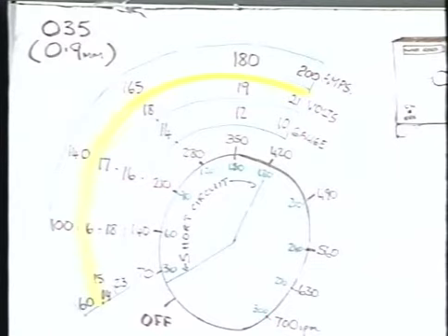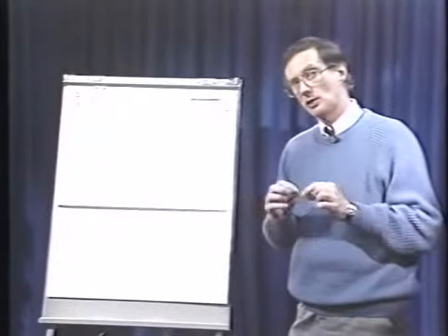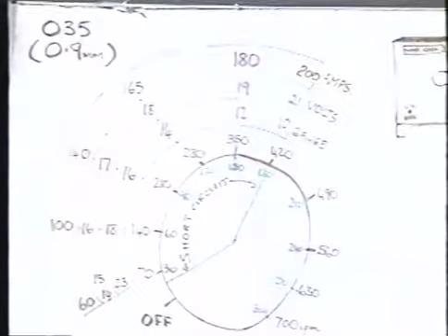A simple setting is as you turn each incremental control one turn, we go up 1 volt. The 9 o'clock position is 16 volts, the 10 o'clock position is 17 volts, the 11 o'clock position is 18 volts. And what about the thickness that we work with in short circuit welding? What about the gauge thickness?